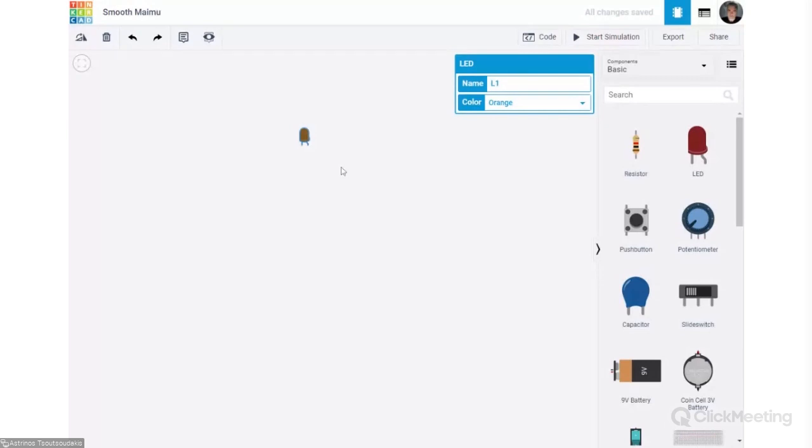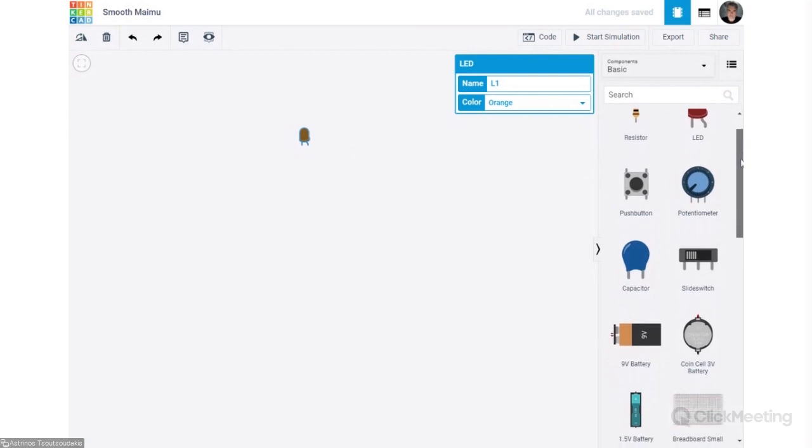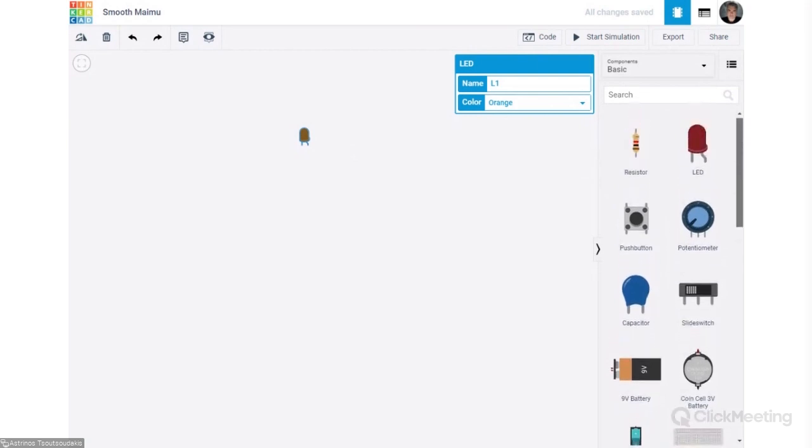But for any LED, you need at least a voltage of 1.2 volts, and you should not exceed the drop voltage, because you will make their life quite short. Or you can end up with burnt LEDs if the voltage of the battery is too high.